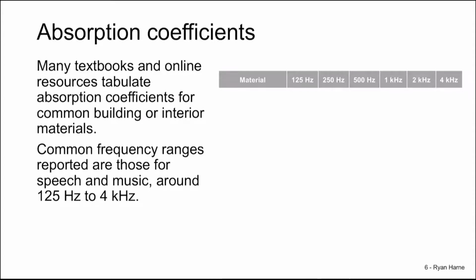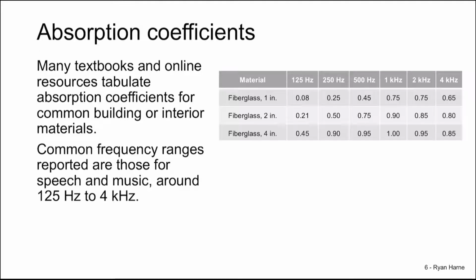We often report these absorption coefficients only from 125 Hz to 4 kHz. And this is because these absorption coefficients at these frequencies are most important to understand and articulate the details of speech and music. So for instance, let's look at a few examples.